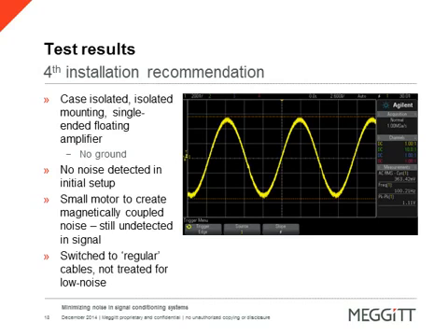So again, this is a system where we have the accelerometer, the mount, the cable, and the amplifier all contributing to an optimum setup. And if you compromise any one of these steps, you're going to introduce noise. You just need to be aware of that.